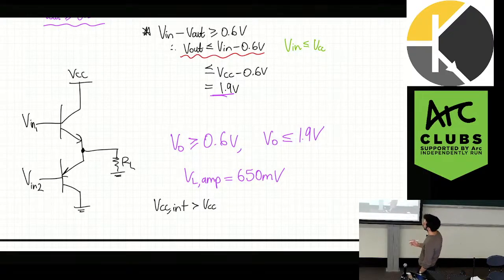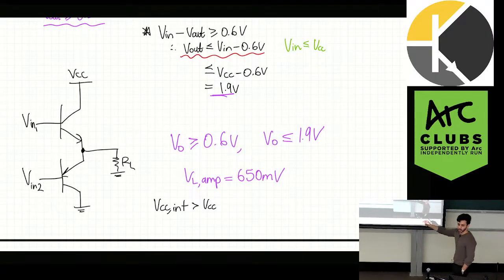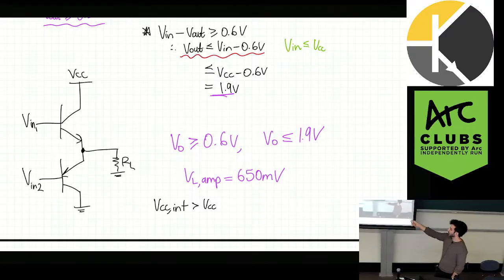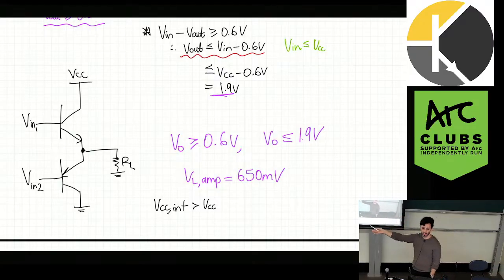One way of thinking about it is we just reached 650 millivolts. But in reality, it's not going to reach 650 millivolts. It's going to reach like 620 millivolts. So we need even more voltage, but at most I have VCC. But we need more than VCC.